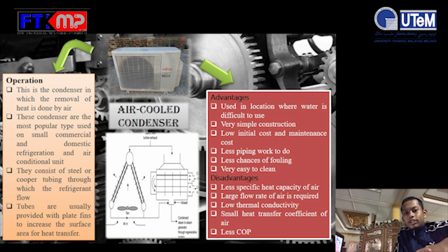The disadvantages of this air-cooled condenser: less specific heat capacity of air, a large flow rate of air is required, low thermal conductivity, small heat transfer coefficient of air, and lastly, less COP.